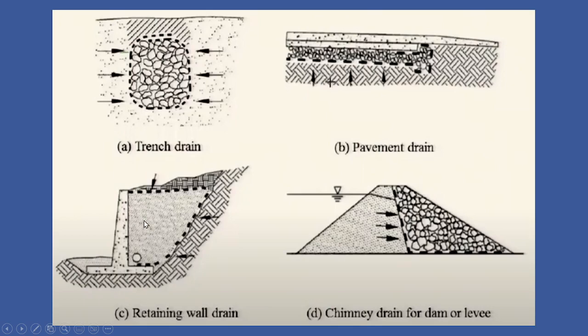So it will provide a passage for the water, and it will further reduce the lateral pressure acting from the soil or the hydrostatic pressure from the water on the retaining wall, and it will increase the strength or reduce the force on the retaining wall.